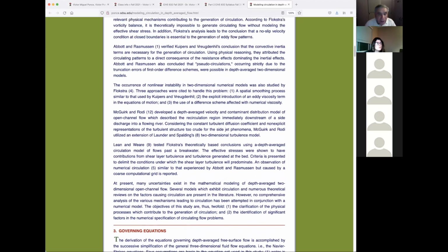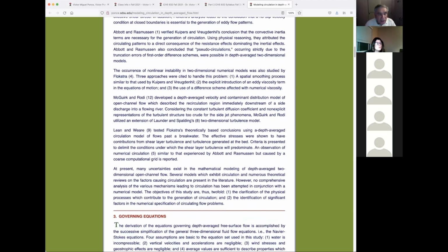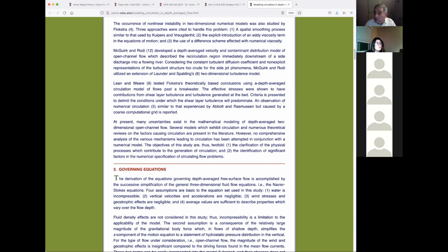And people had suggested that in order to take account of the effective stresses, and I'll talk about that later, you could analog model the effective stresses by an averaging routine. And averaging provides diffusion. The effective stresses were supposed to also provide diffusion. So if you cannot track down the effective stresses in terms of scheme, you could provide a simple scheme that would do the same thing.